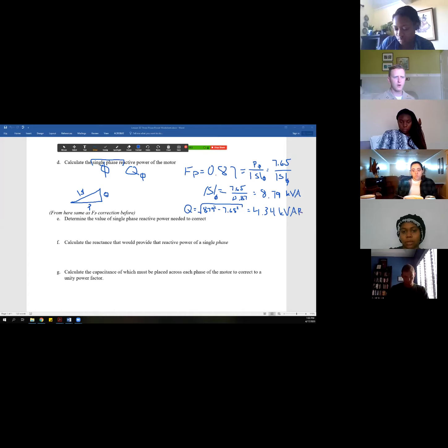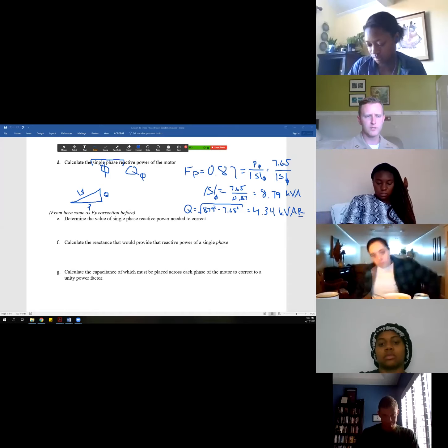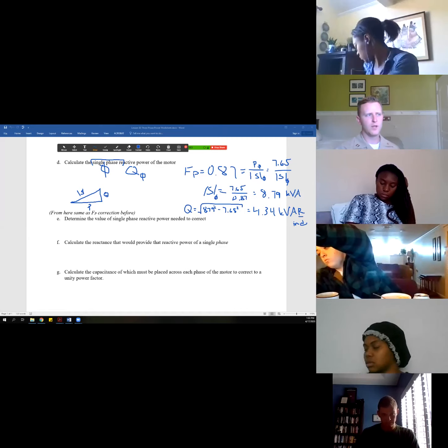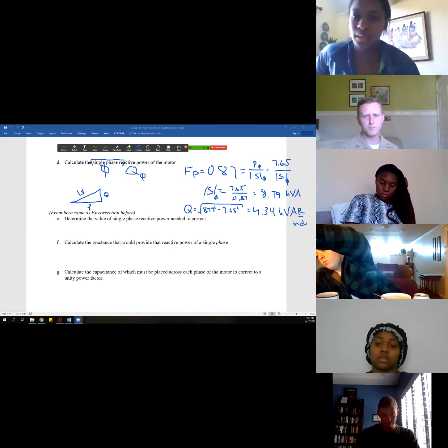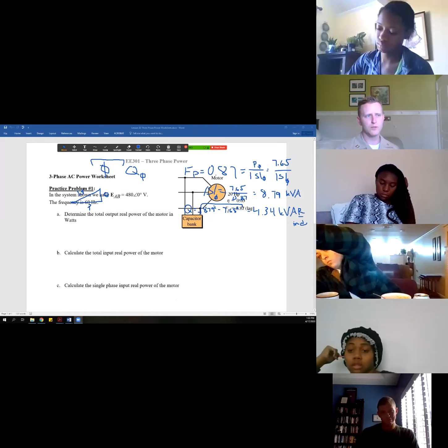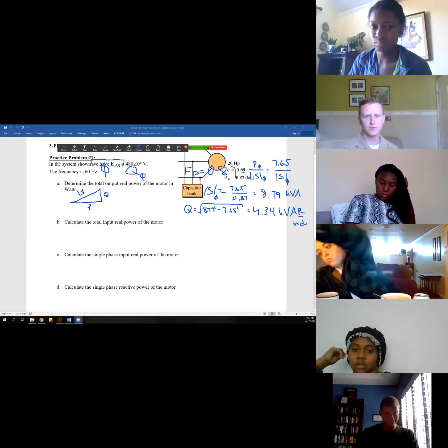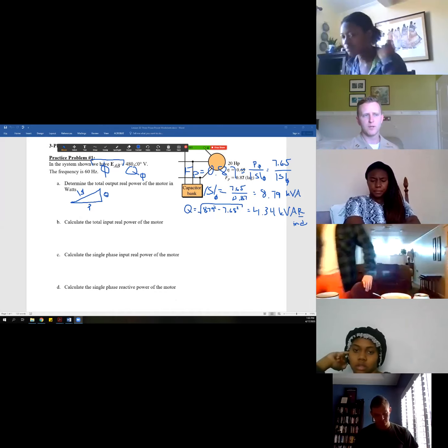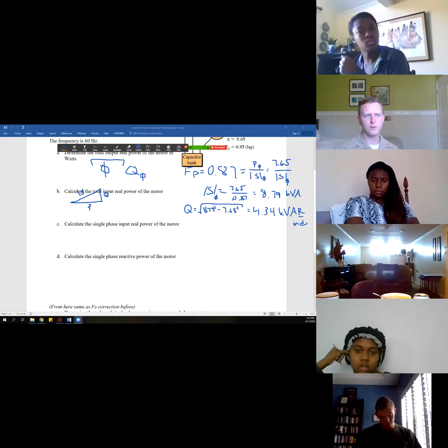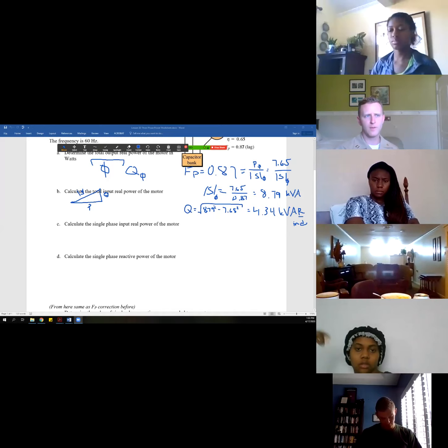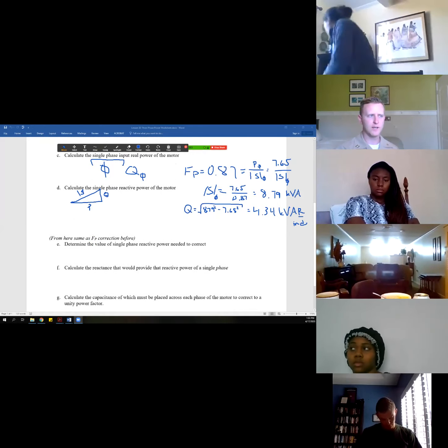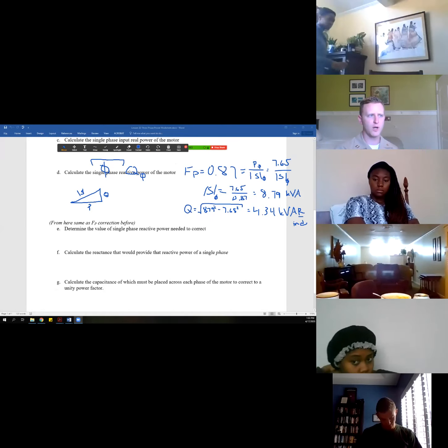kVAR. VAR is volts, amps, reactive, right? That's what the R is, reactive, and it is inductive. And the reason I know that, one, is because pretty much all real motors in the whole world are inductive motors, almost all of them. We rarely have capacitive motors, but the other reason is because it says lagging right here, where it says lag. That word lag, we said lagging power factor means inductive, and I said that's something that you almost just have to memorize in this class.